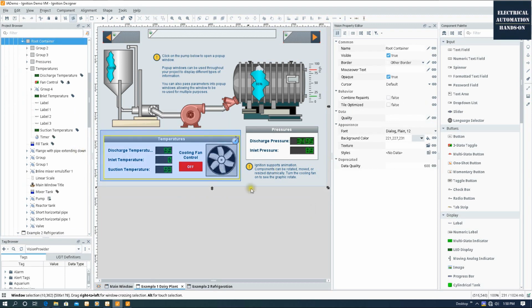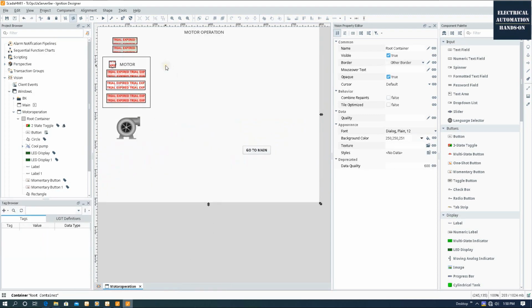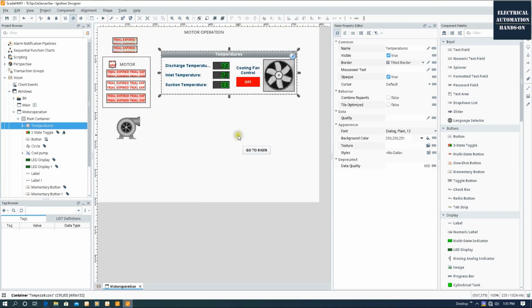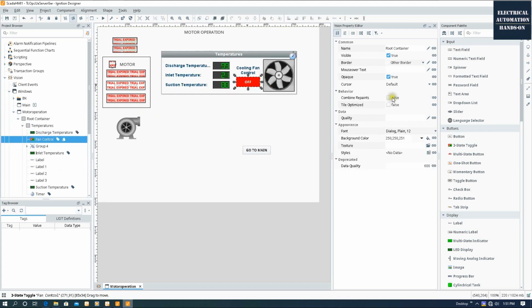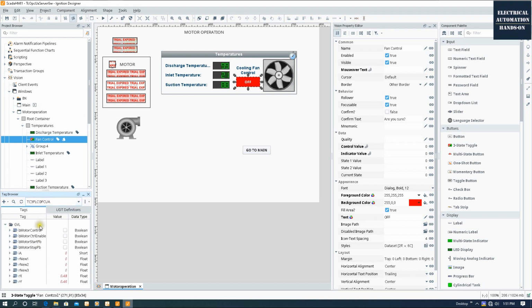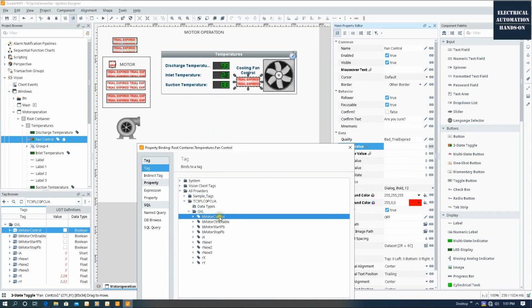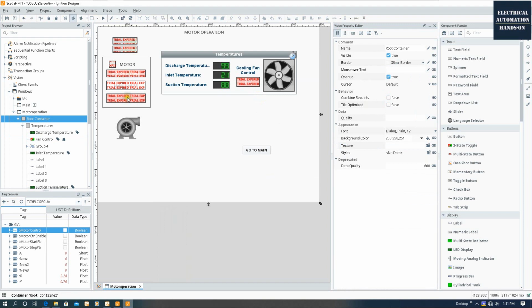Okay, I can copy this entire panel here. Copy, jump to our project, and I can click paste. Okay, so we can see the button behind it has properties here. And then we can connect our tags. I can drag this bool tag to here. Okay, after I drag it here, we can see it connects to this variable. And now if I reactivate that trial license, we will see the project start to run.